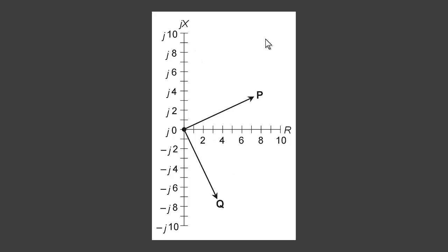Anyway, this particular coordinate system is known as a complex impedance half plane. The vertical axis represents reactance, which are all imaginary quantities as indicated by this J operator, the square root of -1. That's what J represents. So these are all imaginary number quantities. They can be positive imaginary, which represents inductive reactance, or negative imaginary, representing capacitive reactance.